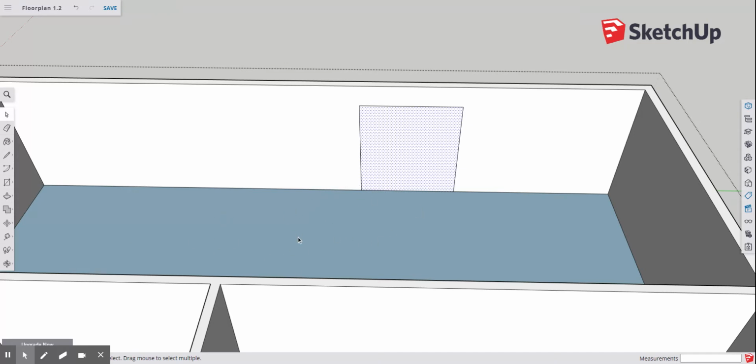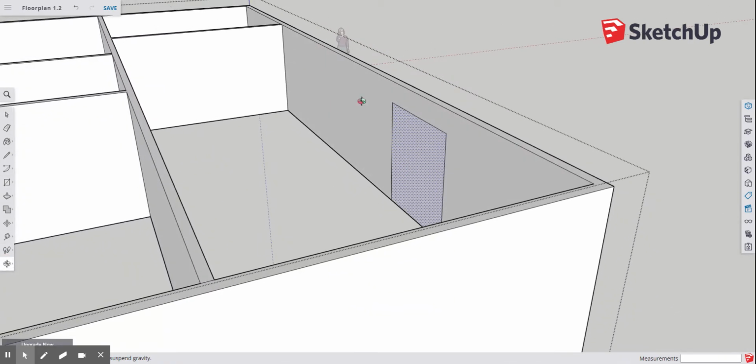Now let's address this surface that I made. It makes surfaces whenever you enclose lines. So let's just select it. It is selected. We can tell because of the dots, and the dots mean it's a surface, and I just click delete on the keyboard and it's gone. Okay, now let's go back to this surface. Let me use my orbit tool. So that's going to be our opening.